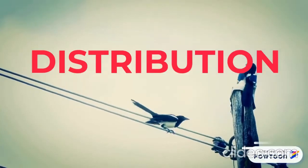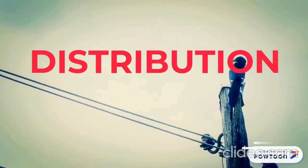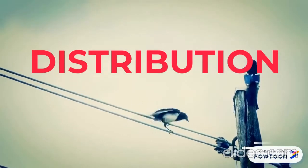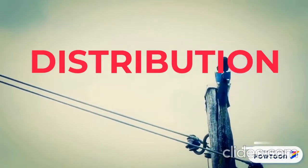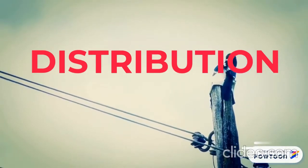Electric distribution is the part of the electric grid where the electric energy is delivered to the consumer. For this purpose, the voltage in the lines is stepped down from high voltages and is divided to medium voltage lines. Each of these delivers electricity to a smaller area. Then, the voltage is stepped down and split once again, creating low voltage lines. These lines are responsible of supplying energy to residential areas for its consumption, and are the ones we usually see in cities or towns.